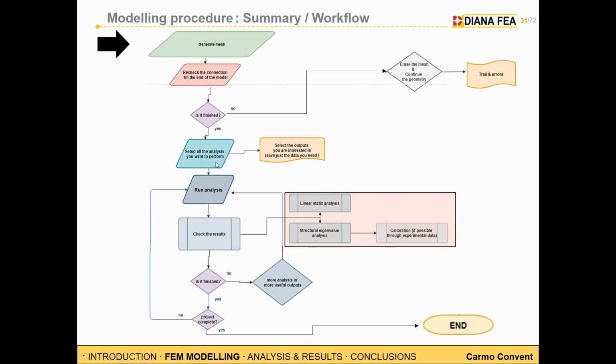Then we can set up all the analyses that we are going to see in detail. But for checking if the model is working properly, I suggest you to always run the linear static analysis and the structural eigenvalue analysis.